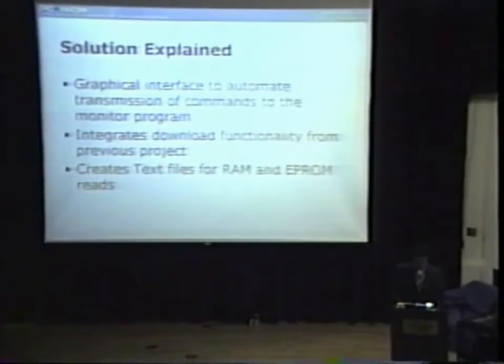Alright, so the solution explained. The graphical interface is used to automate the transmission of commands to the EEPROM. So instead of typing a command, my program sends those commands a lot faster than a user could input them. It integrates the download functionality from previous projects, and it also creates text files of any reads from RAM or EEPROM.